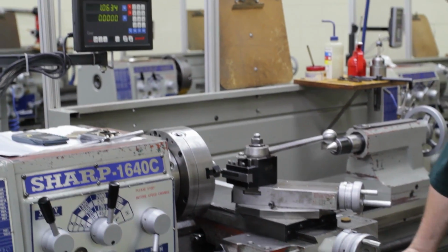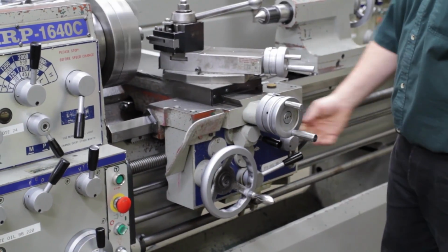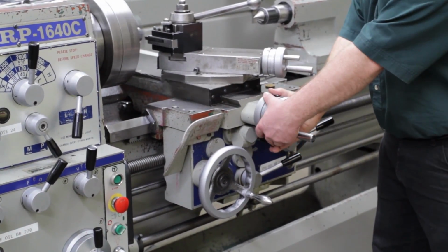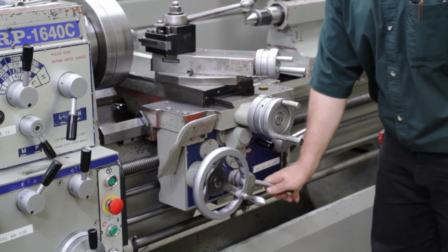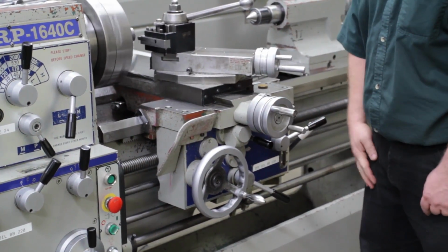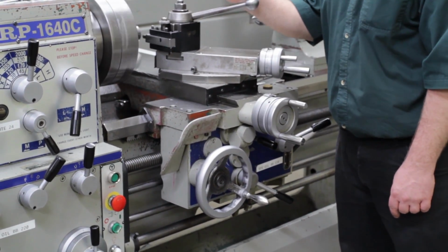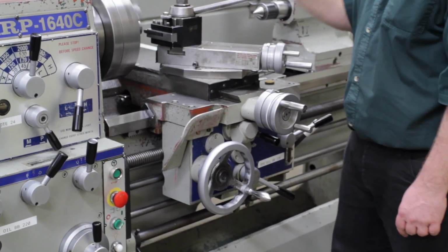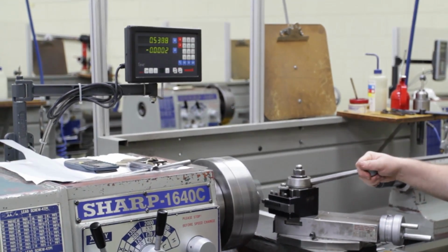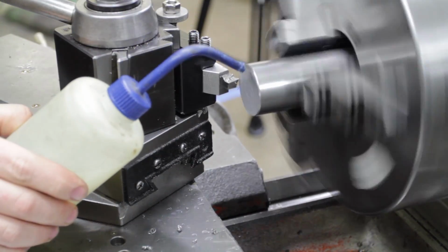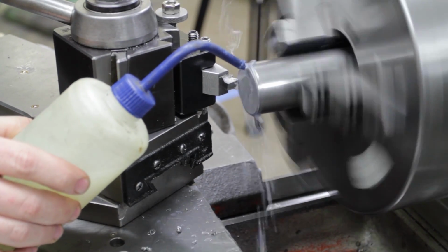So I'm going to restart the machine. Remember, up is forward. This handle is up, so I know it's going to control this hand wheel. So if I push down the feed lever, you see that handle's turning. So while that handle is turning, it's feeding the tool bit across the workpiece. And you'll see on the X-axis that the numbers are counting down. It's a good idea to use a little bit of coolant. It keeps the tool from overheating, and it helps aid the cutting process.